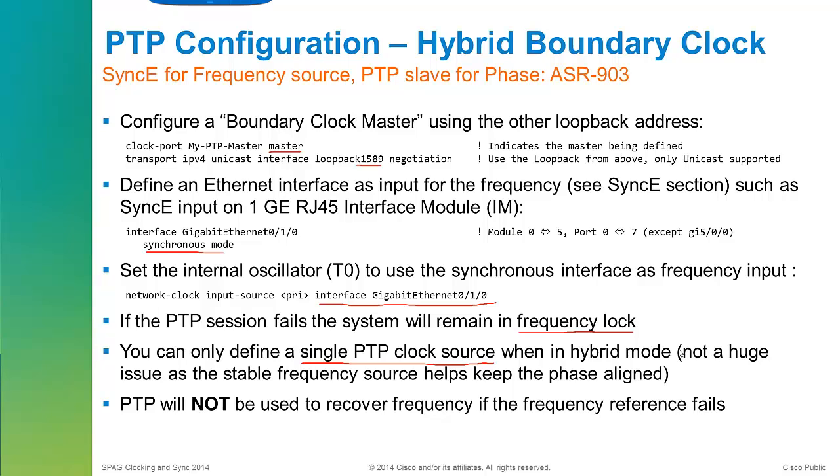So what happens with hybrid mode though is even though you don't have a phase offset, so you don't know how far you are from the car in front, so you don't know if you're 100 meters or 300 meters, but if when you lost the ability to measure how far away you were from the car in front you're 100 meters, and then from that point on you're both doing exactly 100 kilometers an hour, then you will still be 100 meters away.